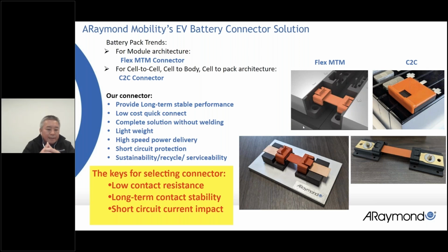As a customer, when you select your connector, you want to look at the low contact resistance, which will reduce your thermal solution, right? It will also reduce your weight. You also want to look at the long-term contact performance stability, which we test and prove.